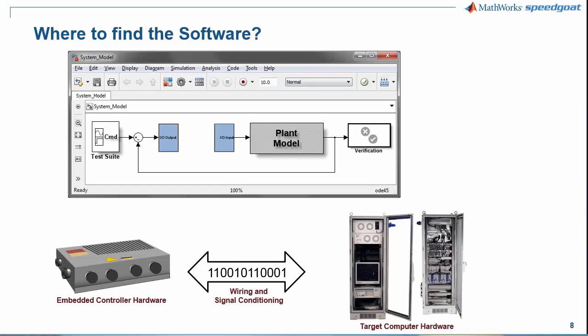You do not need to spend time and money for complex unit integrations in order to test, e.g. a single change in the code base, or to wait until the test track is ready for use. With a setup like this, you can easily test different and dangerous scenarios without any risk of harming human beings or of destroying costly equipment. Adding to that, you can simulate fault injection scenarios, automate testing without great effort, and calibrate the system.